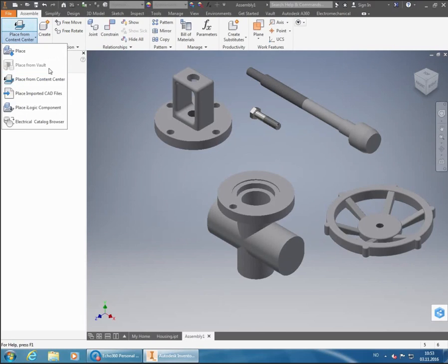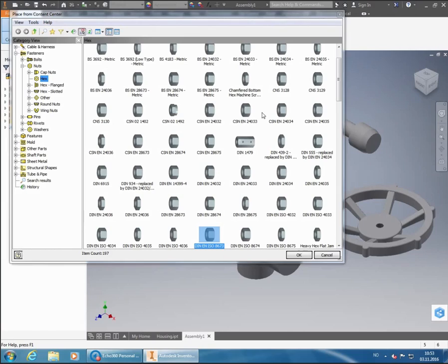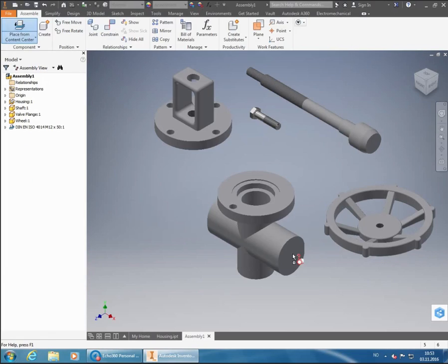Let's see. I'm just going to place it anew here. So 8673, we're not going to hover it across the bolt, but we're going to hover it across the M14 part of our thread on the shaft. That's going to choose M14, and you can even see that it says M14 times 1.5. So it's already figured out that these are fine threads, they're not coarse threads.